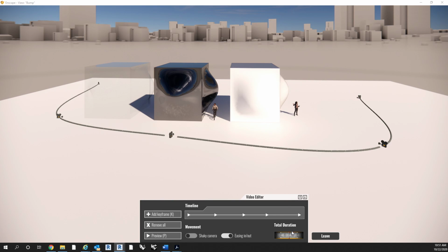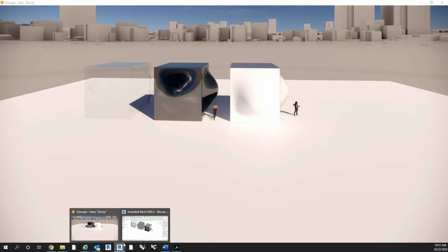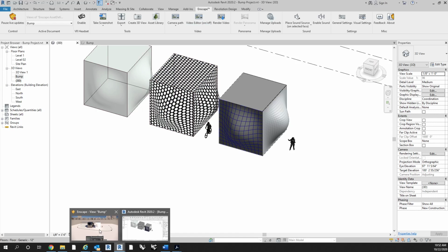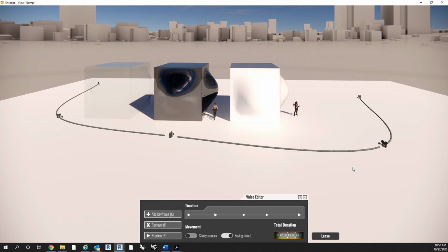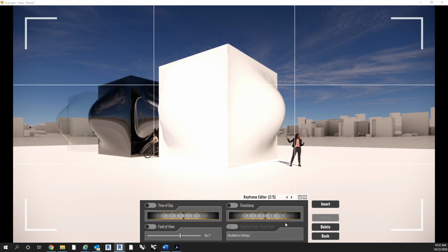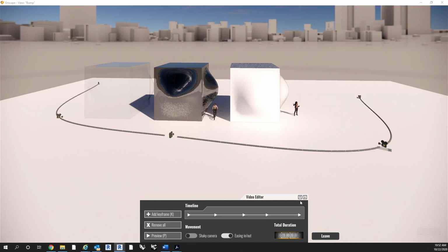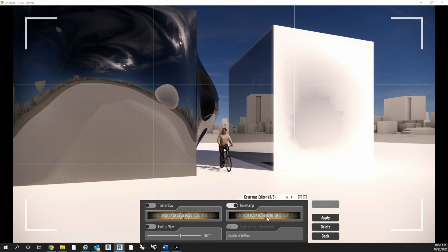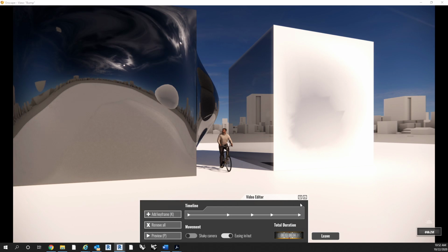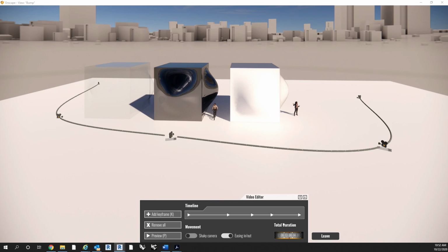The other nice thing that you can do is you can change the speed by changing the duration. So you can actually set up, if you want this camera to, oh no, what happened? Phew, all right, I accidentally hit escape. But if you just go back, turn on camera, it'll pop back on. So if you go in here, you want the first camera to the second camera to be 5 seconds, and then you want the second to third camera to be 8 seconds. You can do that, and you can add that kind of speed to it, and then you can find the total duration of the entire path down here, which is about 12 seconds.